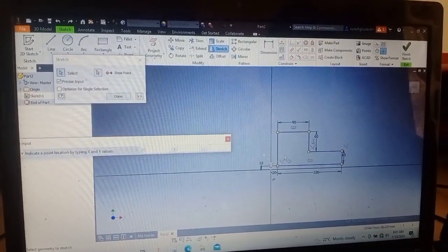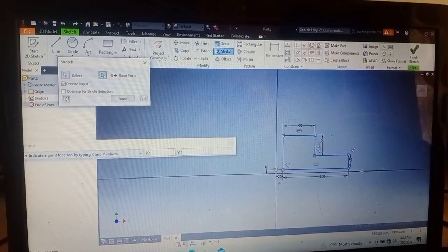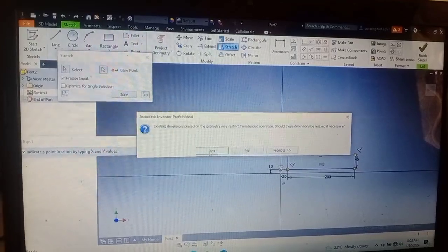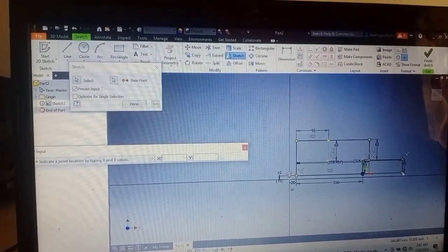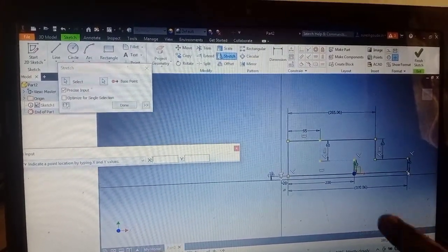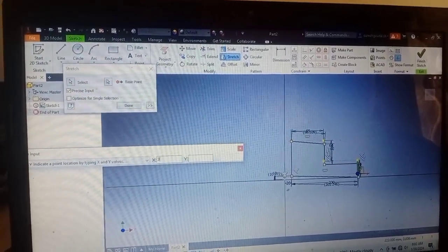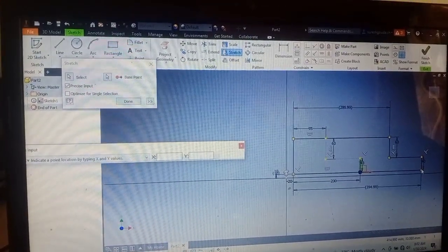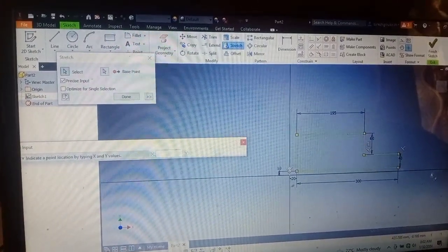For example, in this case, if you select this portion again and select the base point from where to consider the dimension, select S, and here in X I'll enter 300. Earlier the dimension of that side is 200. Now I want to increase by another 100 millimeters. So 100, you can see it is 300.